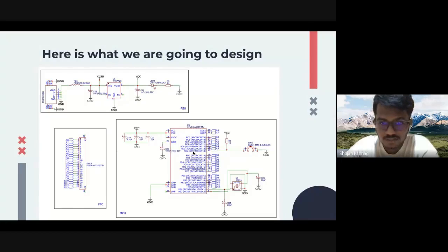And this is the reset, the PC6. You'll get it from your datasheet. Whenever it's pulled high, to 5 volts, through a pull-up resistor I've used, the watchdog timer doesn't interrupt the MCU and call for a reset. But whenever you push this button, it shorts it to the ground.